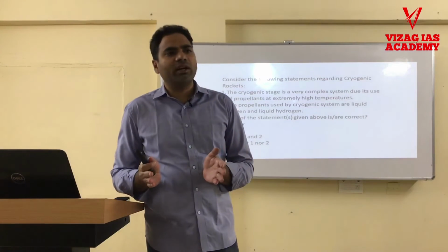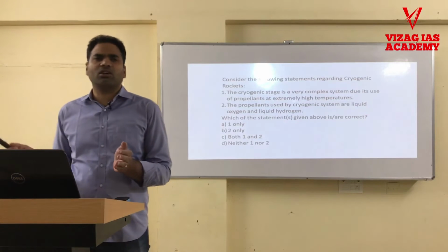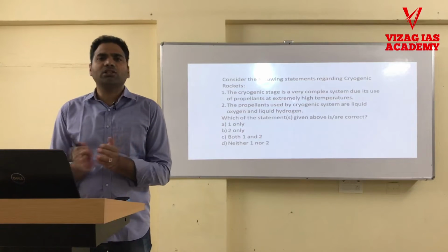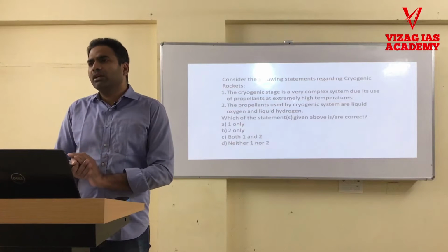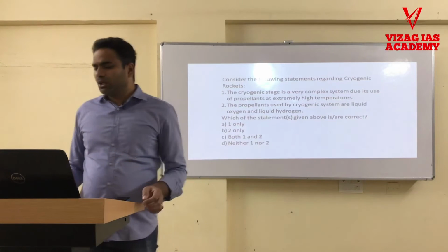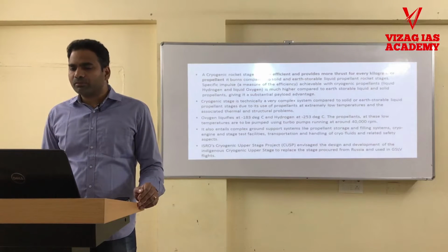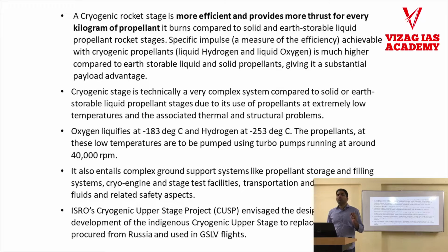Hydrogen has a high calorific value. It is condensed into a liquid form, and the oxidizer, which is oxygen, is also in liquid form. They are combined and pumped at very low temperatures, in liquid form. So it gives a great thrust to the rocket. More thrust for every kilogram of propellant. That is the main advantage of this one.